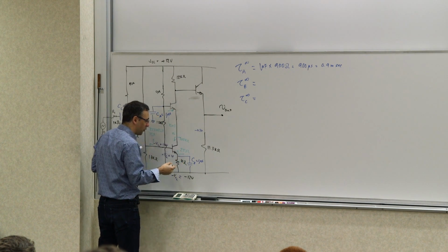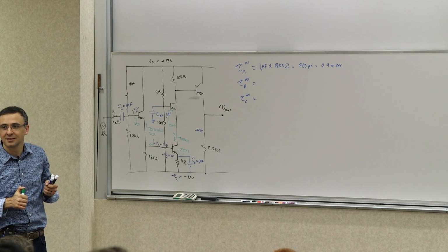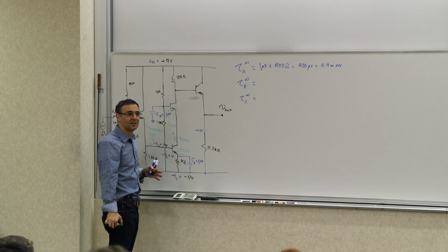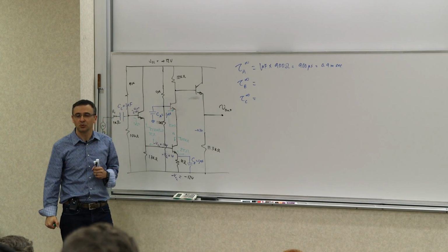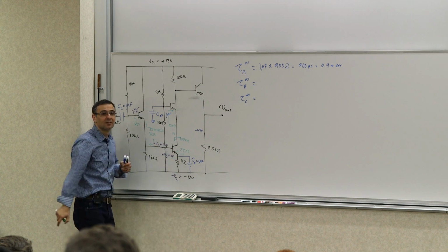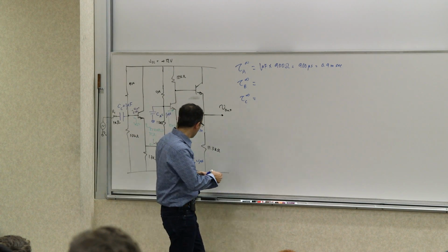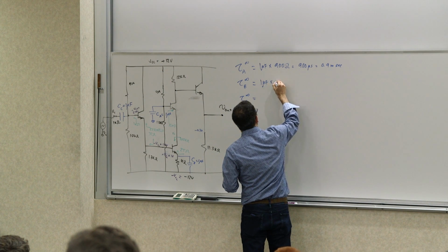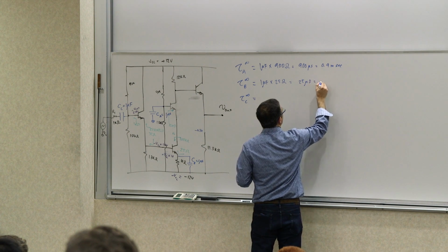I don't need to really worry about the 0.35 ohms. If you want to, you can write 4 significant digits, but it's completely meaningless. Okay? But, so it's 25 ohms. Parallel 1 kilo ohm, it's still 25 ohms. So it's Rm. We know it's Rm. We had to check it, right? to make sure that we are not making wrong assumptions. Okay, so it's 25 ohms times 1 microfarad. So that gives me 25 microseconds, or 0.025 milliseconds.